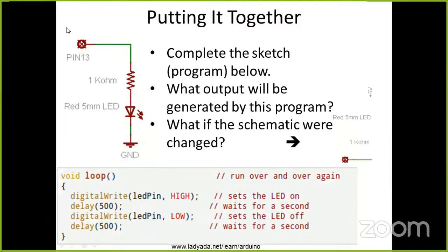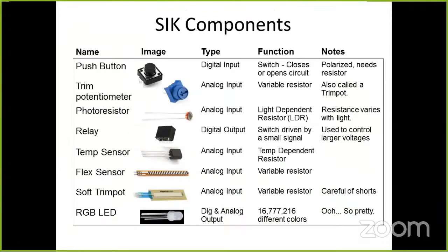So this one is a simple circuit, like earlier we have done for the LED. So how to write code for LED on off? This one is the code over here: digital write, LED pin, whichever pin we are using, like 13, 12, 11, that is high. Then delay in milliseconds. So it will wait for 1500 milliseconds. Then digital write, LED pin, that is low, then the delay. The code we have written in graphical form also earlier, that is the same code.